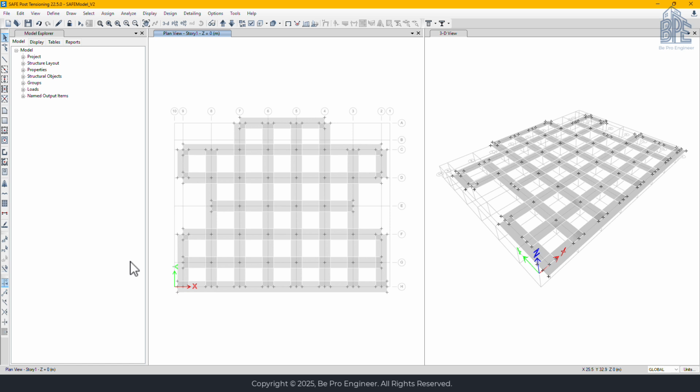Okay, let's now clean up the geometry of these area elements, especially at the ends where the corners might not be perfectly aligned. Now, we just need to snap these nodes to the ends of the foundation strips. So, I'm selecting these nodes, and we want their x coordinates to match this point right here. It means we'll set them to 0.5.